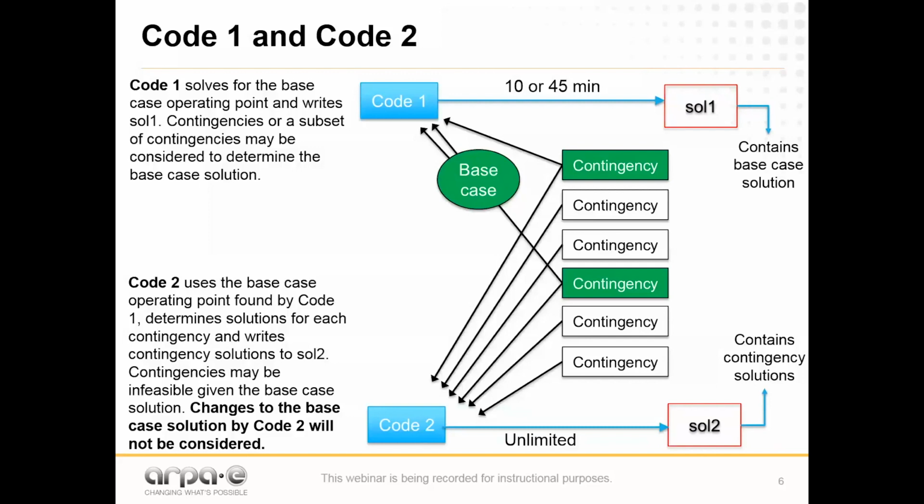The other question was what, Dave? The distinction between hard and soft constraints. Okay. Different people mean different things when they say a hard constraint or a soft constraint, but basically what you should take away is that soft constraints are the ones we have relaxed. We have put slack variables on some of the constraints. Again, refer back to the formulation. With those slack variables, they show up in the objective function. You will see that in the formulation, and they have penalties associated to them.